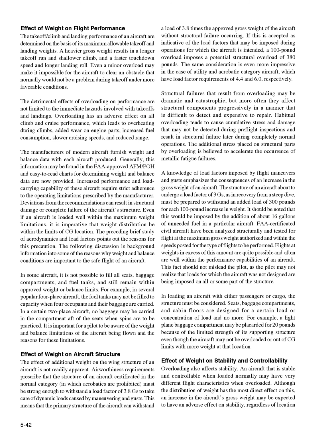Effect of weight on flight performance. The takeoff/climb and landing performance of an aircraft are determined on the basis of its maximum allowable takeoff and landing weights. A heavier gross weight results in a longer takeoff run and shallower climb, and a faster touchdown speed and longer landing roll. Even a minor overload may make it impossible for the aircraft to clear an obstacle that normally would not be a problem during takeoff under more favorable conditions.